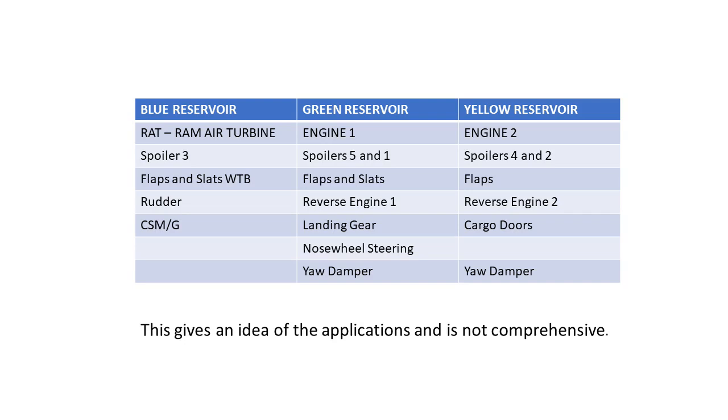There's also a seal drain system that's responsible for collecting any potential fluid leakage from any of the components, and this keeps it away from the aircraft structure, which, if we find it there, could be a potential fire hazard. After the main landing gear compartment are the 3 ground service panels, one for each of the systems. The blue and green service ground panels are in the left belly fairing, and the yellow in the right belly fairing, and you'll see that on the diagram.